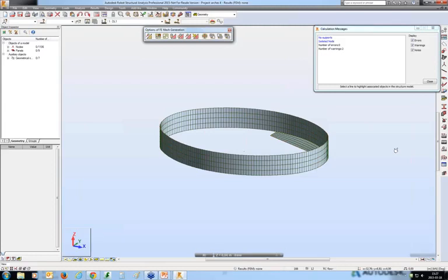One is such that you have the mesh frozen, and then the mesh is erased and generated again only when you use local meshing for this panel. Or when the mesh is not frozen, then it is done either when you run local meshing or when you run model generation, which includes the generation of the meshes from unfrozen panels in the entire structure.